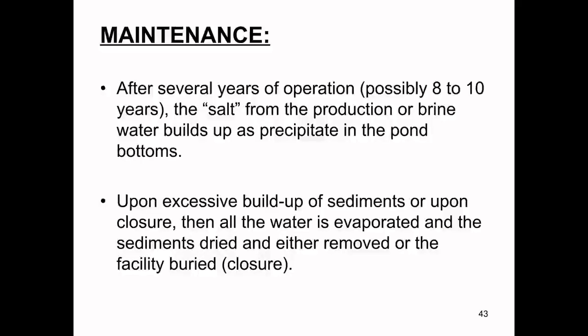So maintenance: after several years of operation, possibly 8 to 10, depending on how much dissolved solids are in this water, the brine or its salts build up in the pond, and if it does excessively build up, then the sludge or the sediments need to be removed, and either removed or buried on the facility. It depends on the state, but some regulations allow that material to be buried if the material doesn't have a high amount of oil in it.